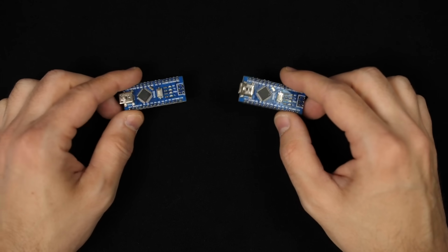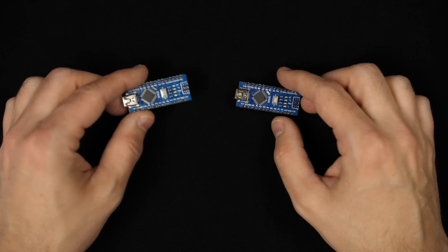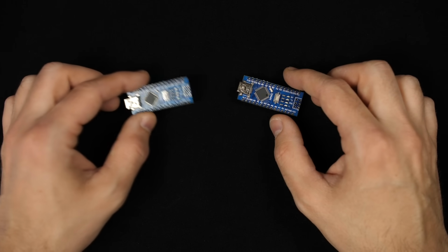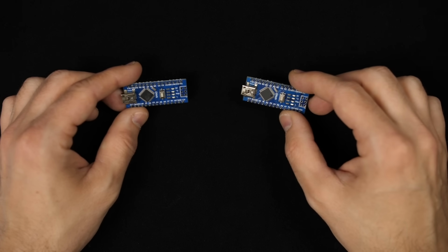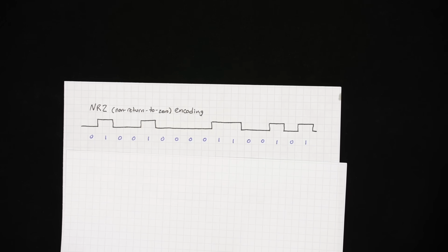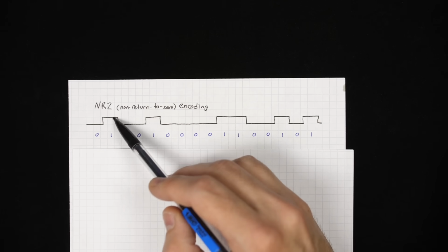And for computers, I'm going to use these Arduino Nanos. So what's the most basic thing we can do to transmit information from one of these Arduinos and receive it correctly on the other? Well, if we're going to program one of these as a transmitter that's going to send some data, and we'll program the other as a receiver, let's start by figuring out how the transmitter is going to work. Well, one of the simplest ways to send data is with one data line that has two levels. If it's low, that means we're sending a 0, and if it's high, that means we're sending a 1.